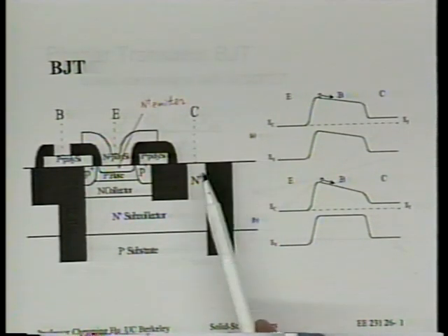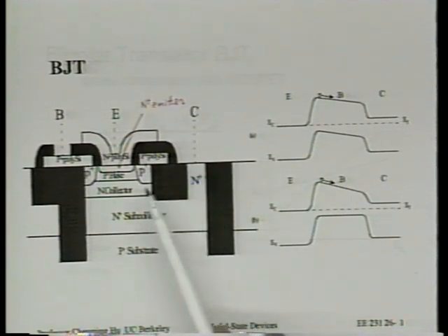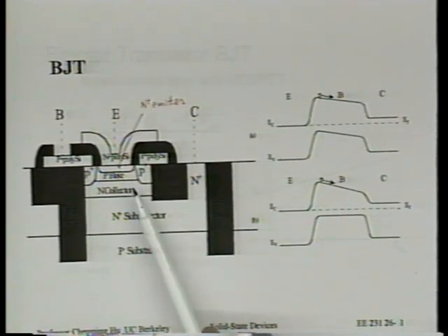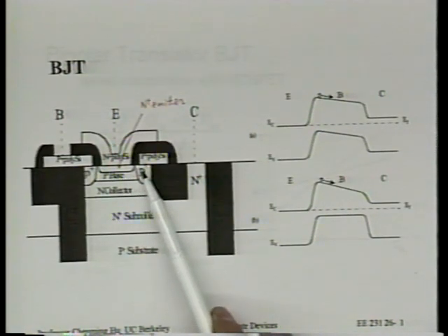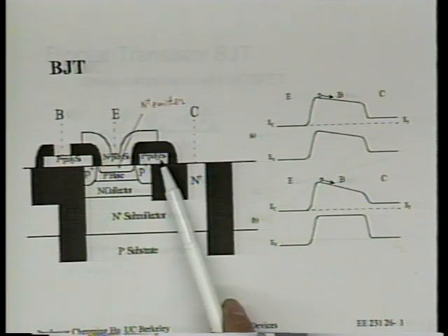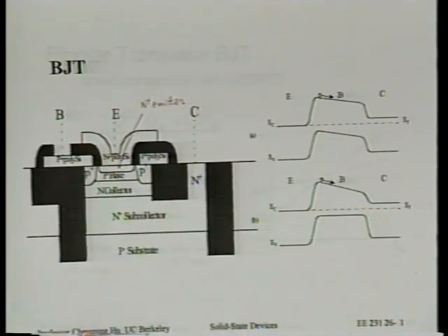All right? We need to make a contact to the collector, and we need to make a contact to the base. We need to make a contact to the emitter. Contact is where the old design takes most room, but in this current design, you can see how we make the transistor small. How do we make contact to the base first? We make contact to the base by connecting the base to a little bit of P plus region. And the P plus region is connected to a P plus polysilicon. And polysilicon sits on oxide. Okay? So that's how we make contact to the base.